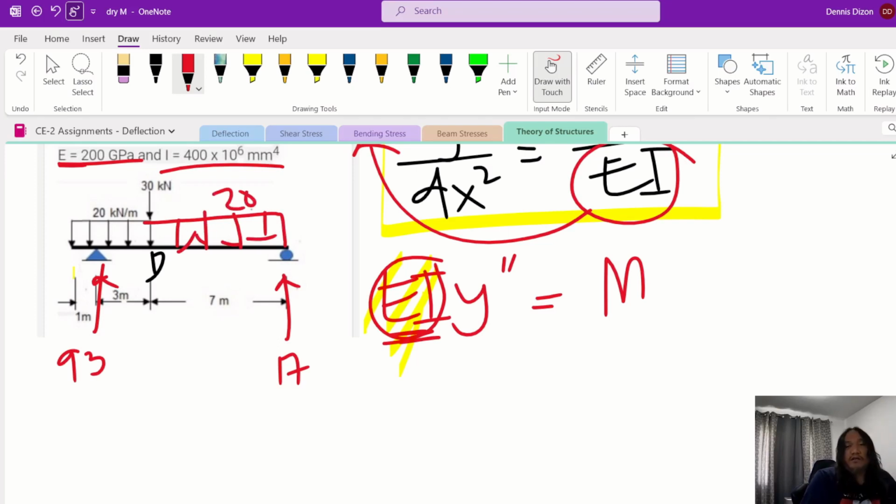Since you add a portion of uniform load at the bottom of your beam, to counter that, you have to add the same load, the same quantity, the same length, but going up. It is as if you add, say, 500 kilonewton going down and also 500 kilonewton going up, so that would cancel out. So this is the same as just the original load.